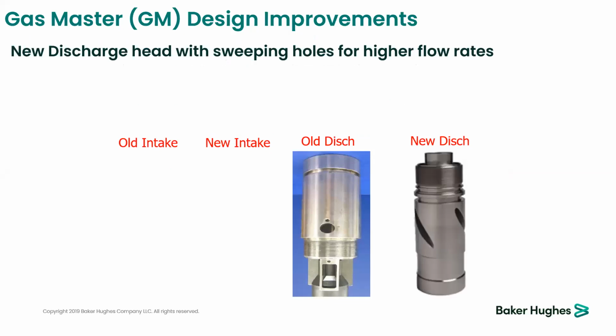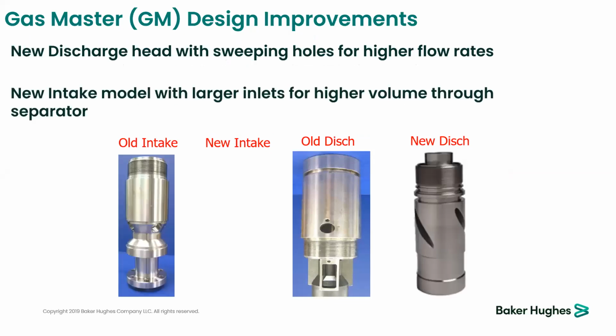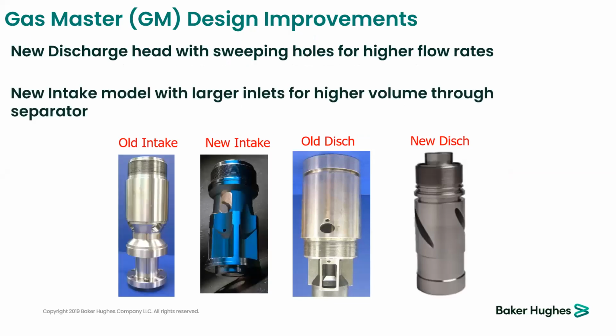Here are some photos of the old intake and the new intake. The only difference is the port. If you look, the port is narrow in the old intake, while in the new intake the port is wider and has an angle, which decreases the possibility of plugging of the intake ports.